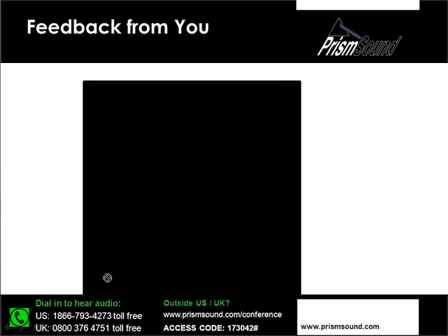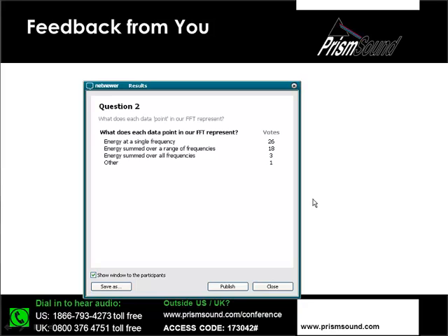So let's look at your responses. And I can see that a distinct majority of you have responded that you believe that the information contained at each data point in our FFT represents the energy at a single frequency. I can tell you that actually the data points in our FFT represent the energy summed over a range of frequencies, and this is going to feed into the discussion in the next section. So I just wanted to ask you that and clarify the correct answer to the question before we move on.